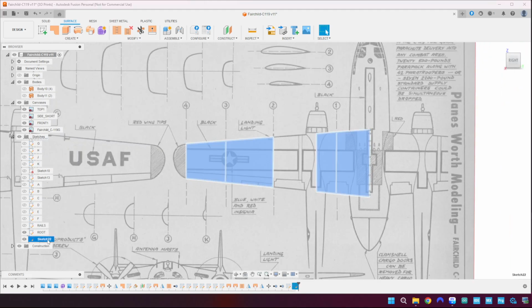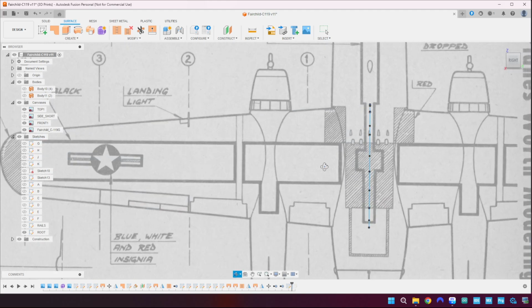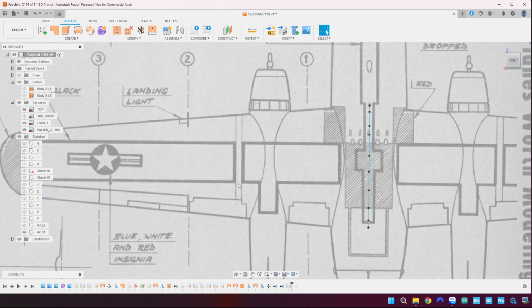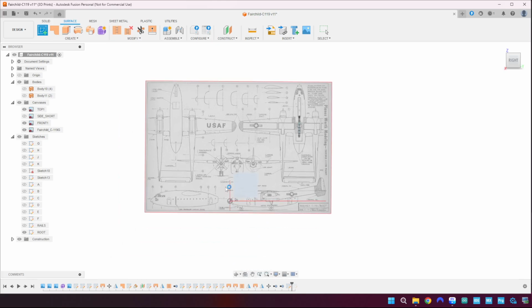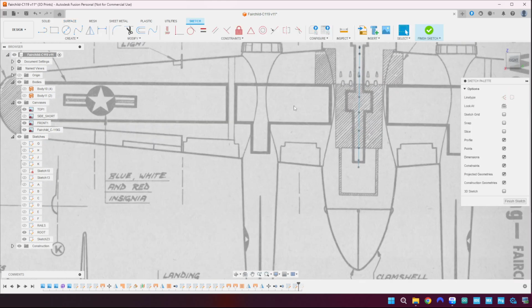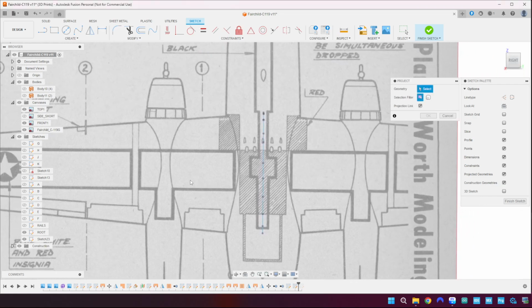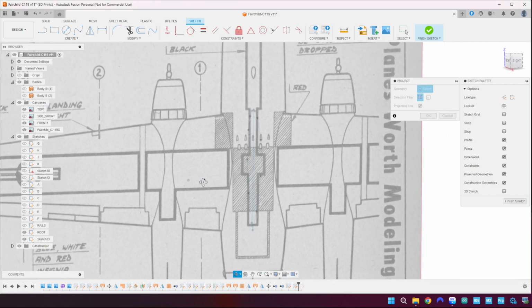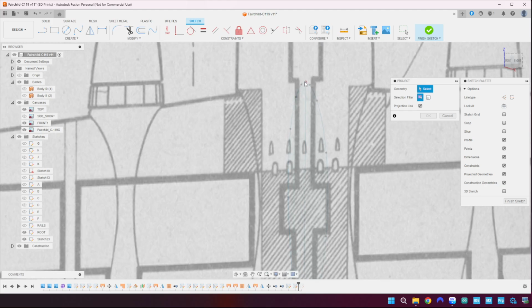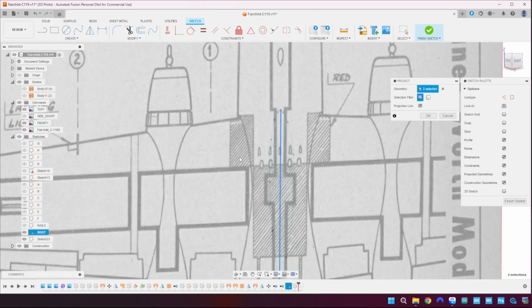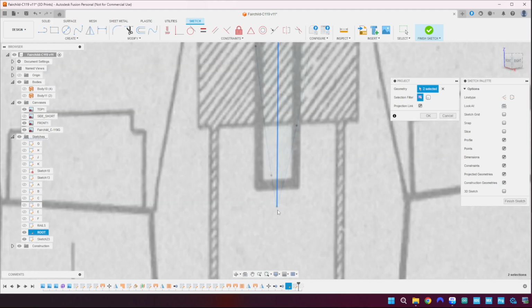So that is that sketch there. I can remove that one. So we're removing that, and the sketch I want now is a new sketch on that plane. I need to project that point, that line, and I want to project this point as well. Okay,